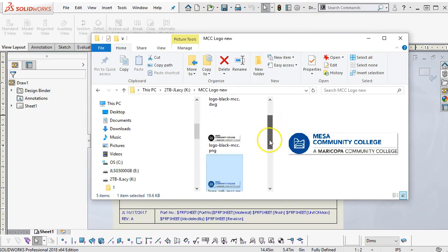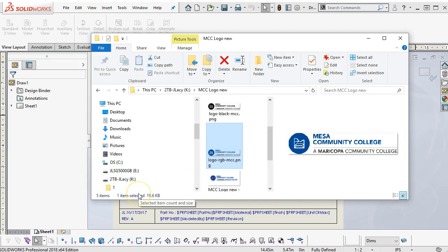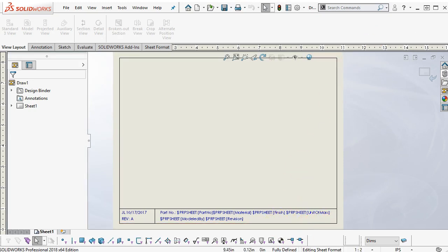One of the things with the logo is that it will accumulate whatever size and whatever resolution you bring into the sheet. So this logo is 19 kilobytes, this one is 247. If I have 20 sheets, that's 20 times 20. If it was a 1 meg logo, I would have very nice resolution. But seeing how we're putting it in the bottom corner, you really wouldn't be able to notice the resolution for the dots per inch that the printer's capable of. So you would not really be gaining anything, and your 20-page drawing package would all of a sudden be at least 20 meg. Every sheet is going to contain that logo.